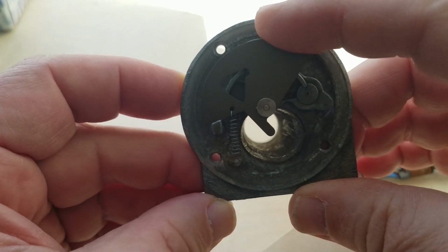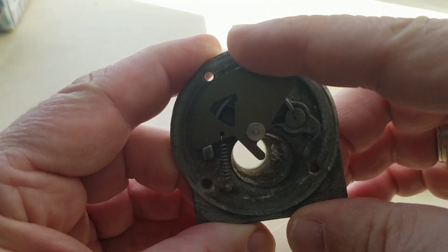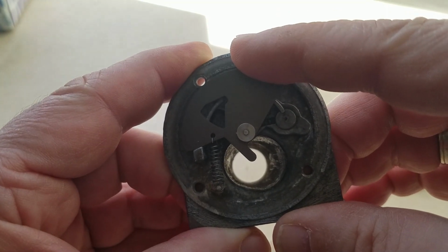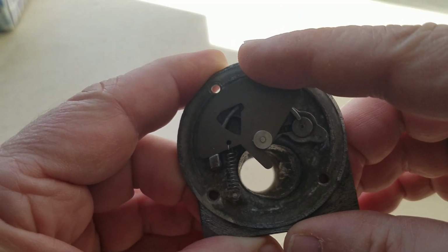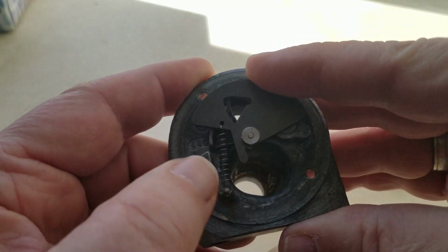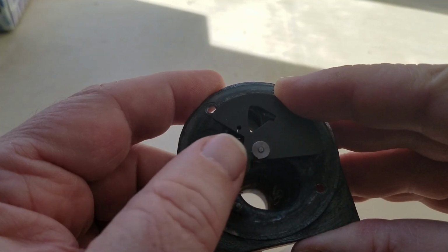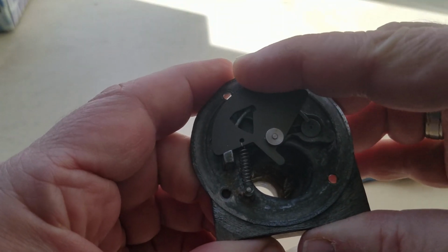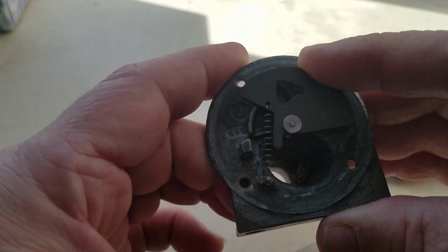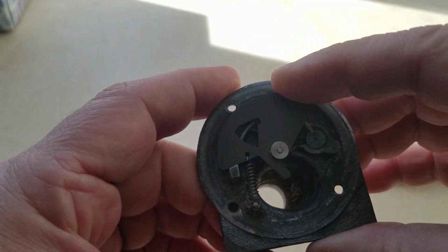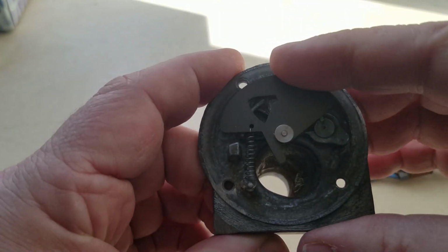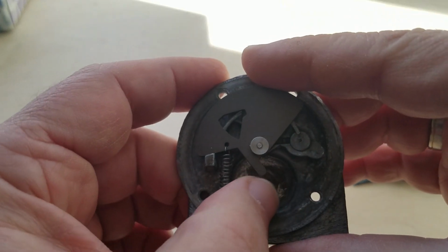So the two things that are important is that A, the spring extends and that increases the force. So I needed to measure the spring constant, and also the spring moves, as you can see, towards the center of rotation with increased angle, and that means that the moment around this point is being reduced, and that has an impact on the actual force that the spring exerts on the shutter here, and then on this little finger.